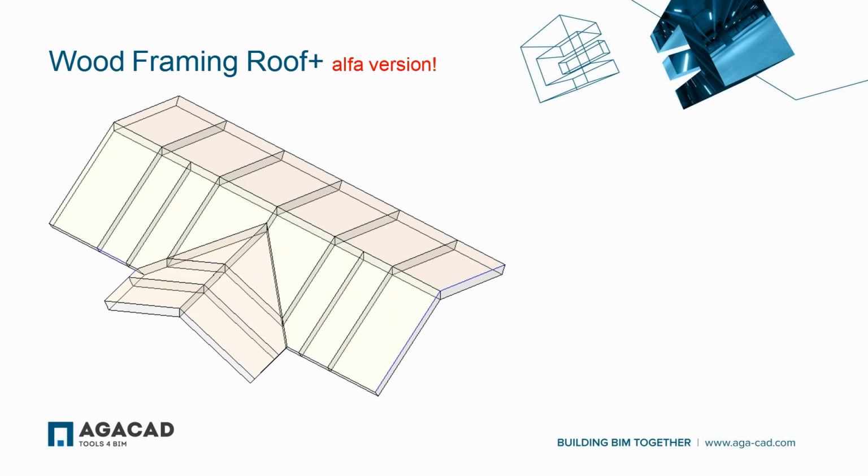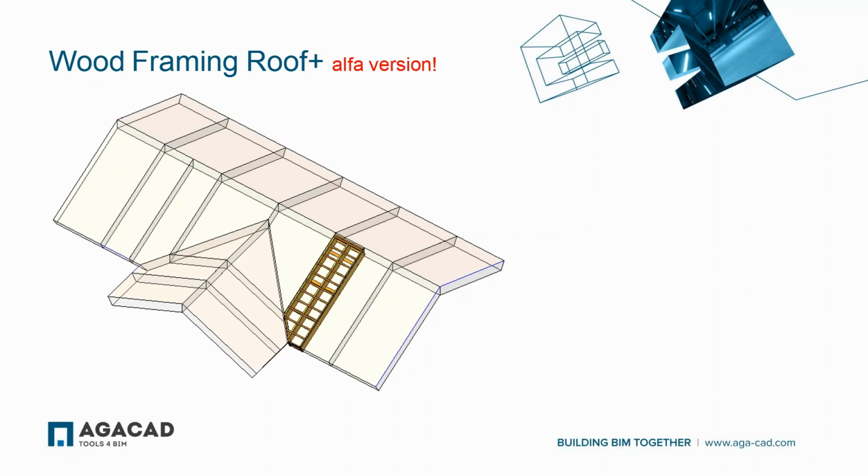Then next step, the tool splits the roof into the segments. Actually, physically, it leaves the existing architectural roof, and on top of that, it's adding roof panels, and it adds it into the construction phase. So in this case, you are going to have 2 roofs in one place. So it will be one architectural, because we can't delete it, because maybe architects could be using it, or you can make a link, you know, and you can link architectural model to the structural project. So here we're creating the roof panels according to the layouts which were created before, and then you can frame it the same as we did today with the walls.